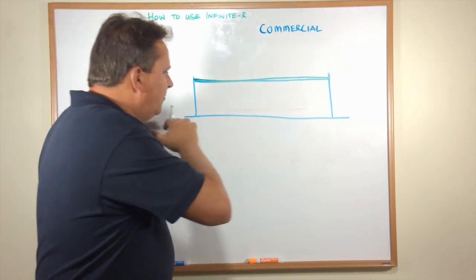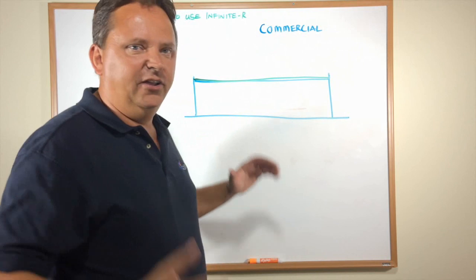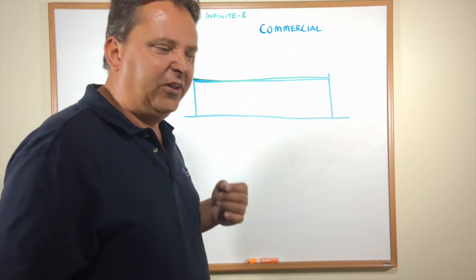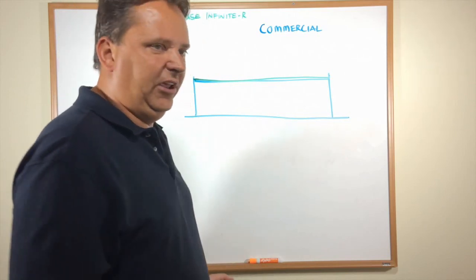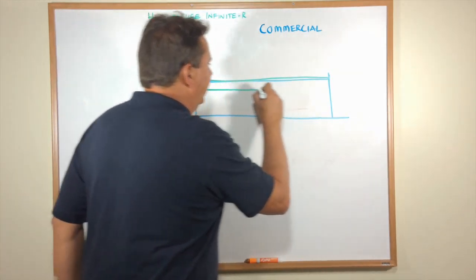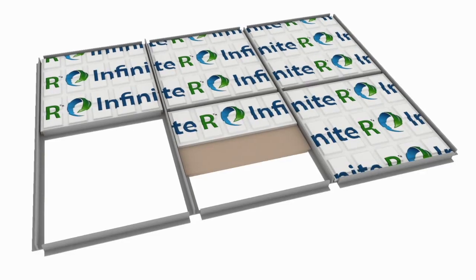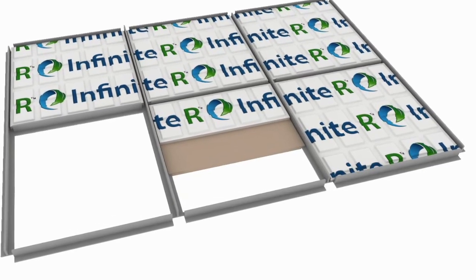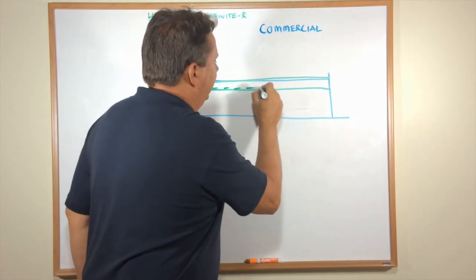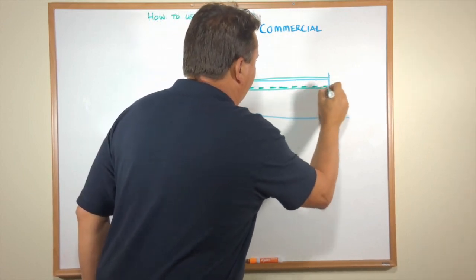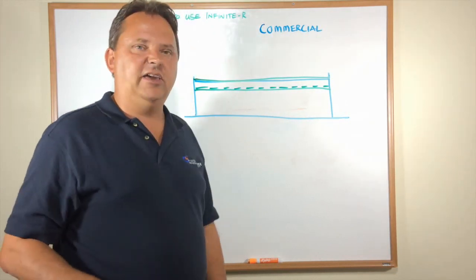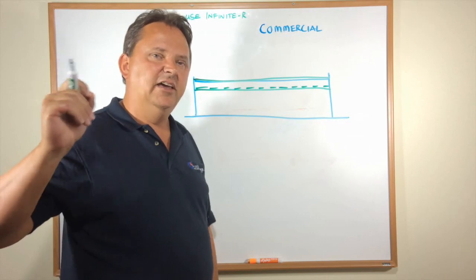Because large retail stores have so much roof area, this is always the first area that you want to look at. Now there's a second way to do buildings if you can't get access to the roof. Say you're retrofitting, or there's something in the roof sector that doesn't allow you to have phase change. Another option we have is to put the phase change over the ceiling tiles. So we basically pop up the ceiling tile, lay a bunch of phase change around it, move on down 10 feet and do so again. By doing this, we actually create a thermal layer within the ceiling itself, thus dropping the temperature of the roof and thus reducing the amount of heat that's being transferred from the ceiling into the building.